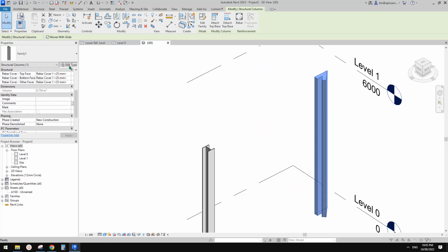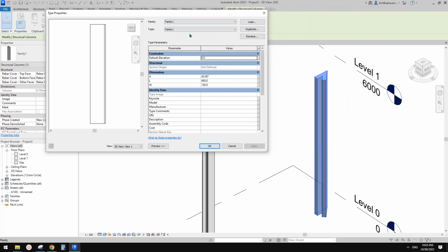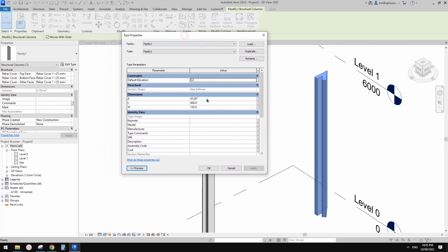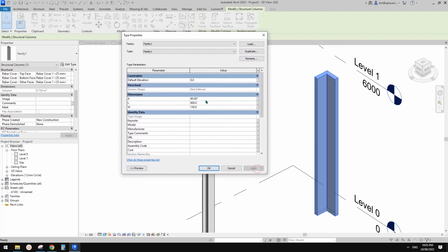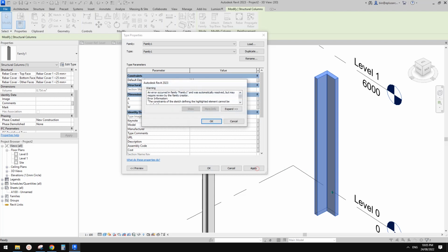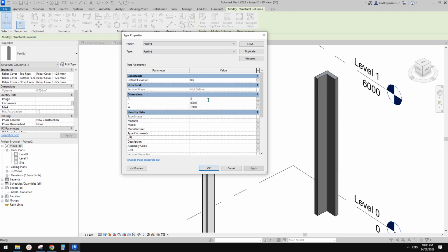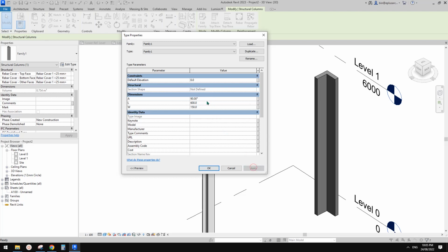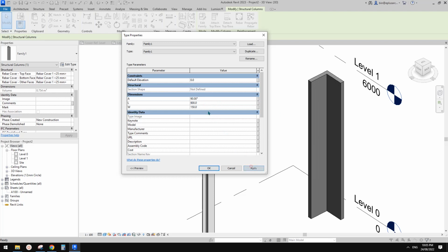So now let's have a test. We have all the parameters because they are all type parameters. Let me just turn off this. How do I turn this one off? Oh, this one. Okay, so 45 degree. Always try the 90 degree. I don't think 0 degree will work because this extrusion will break at 0 degree, right? So maybe it's 30. It's very close, almost. Yeah, so 45, 90, and 600. Try 900, 300, and that's it.